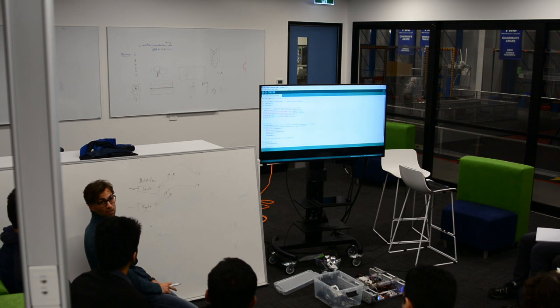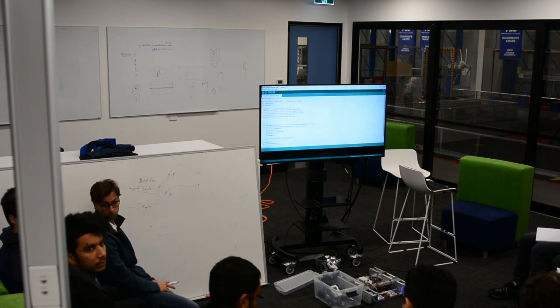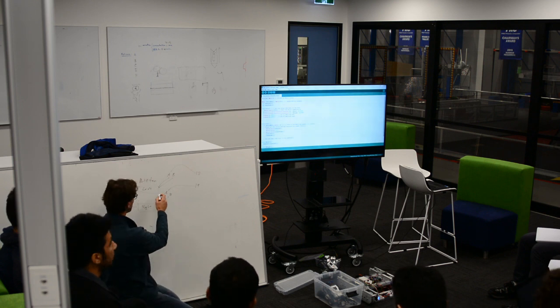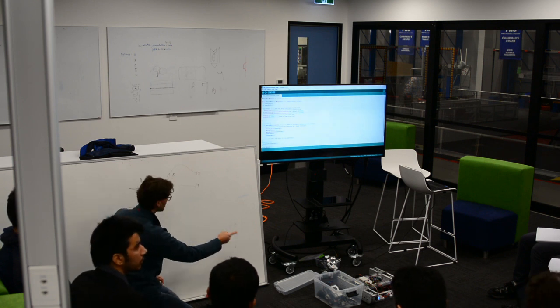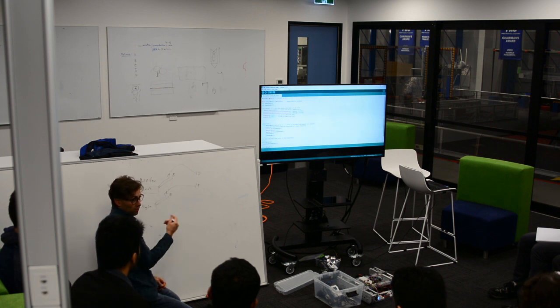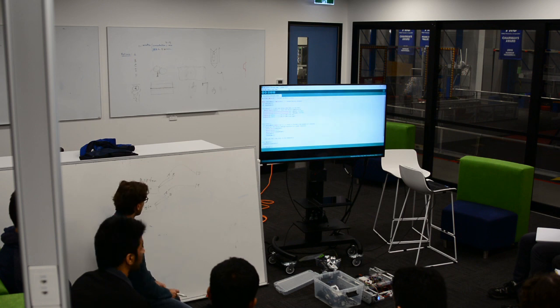Yeah, Rex. They actually have 4 motors. Oh, they have 4, so we're talking about 1 motor on each side. Oh, that's right. But they're chained together. So right now, the way I've done it here is I've only hooked up one of the motors to the interrupt, even though there are actually 2 motors on the left and 2 motors on the right. I'm not worrying about the other motors because they've got that belt that connects them all. So I'm going to assume they're all doing the same thing.